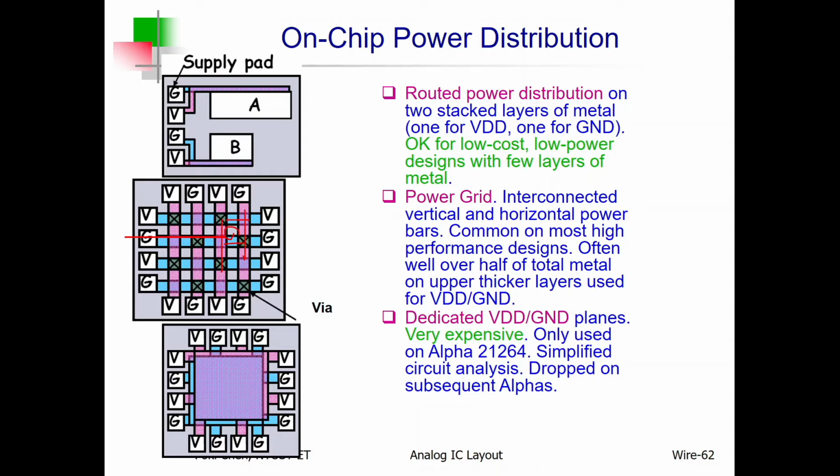However, if your chip consumes even more power, then you need to apply such dedicated VDD and ground. It looks like this, but with many more than 2 blocks, and each block needs to have its own VDD and ground. It will be more expensive than a power grid. It's up to you.